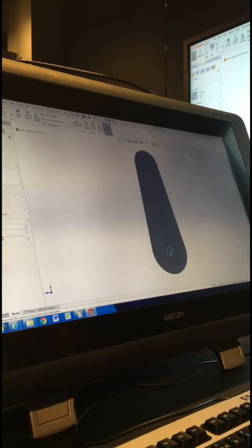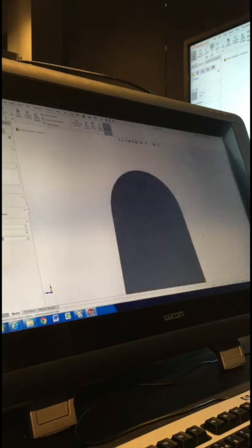All right. Up the top, there's no origin to click on, but if I hover my cursor over the arc around the outside edge, it'll show me the center point. And once that center point is showing, I can click on the center point and drop that next circle. All right, and that's adding a coincident relation between the arc and the center point of your new circle.